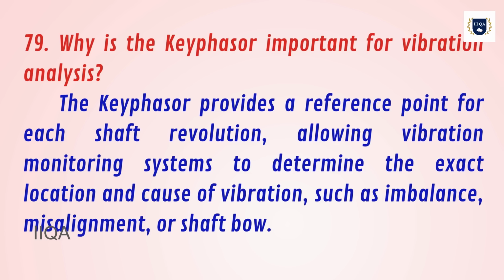79. Why is the Keyphasor important for vibration analysis? The Keyphasor provides a reference point for each shaft revolution, allowing vibration monitoring systems to determine the exact location and cause of vibration, such as imbalance, misalignment, or shaft bow.